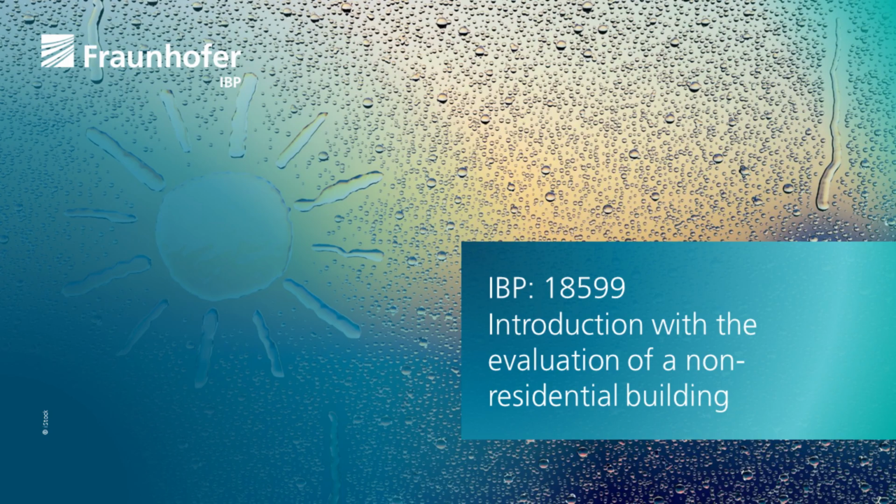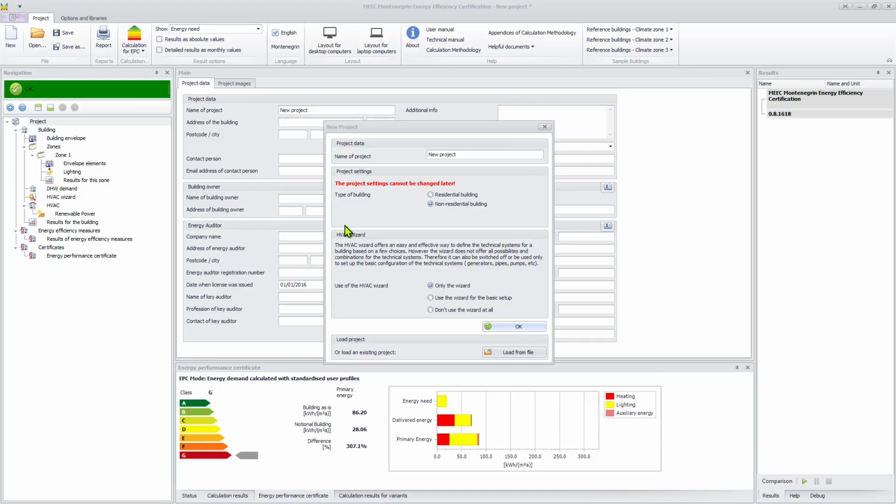We will start by creating a new project. The new project window will appear automatically when you start the software. Here we can create a new project. We will name the project Introduction Project. The type of the building will be non-residential, and we use only the wizard in the HVAC wizard settings. Finally, we click on the OK button.